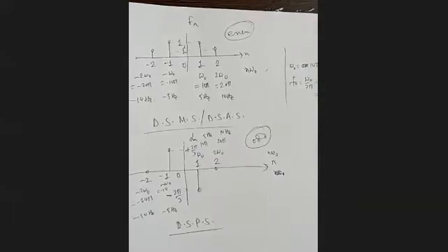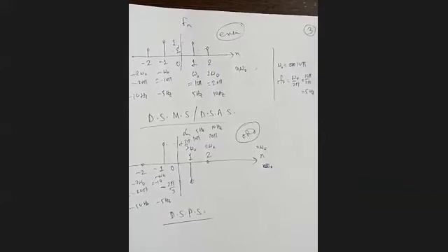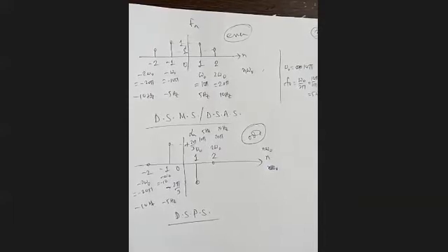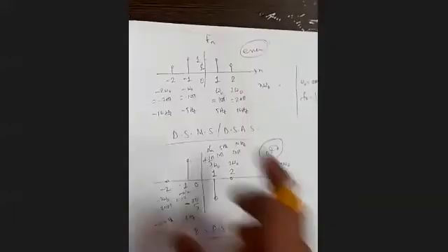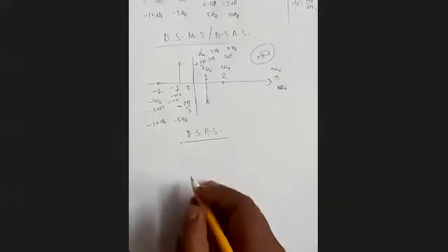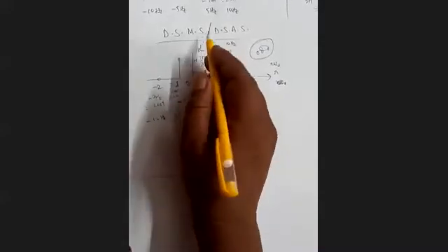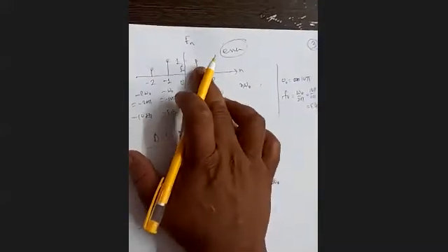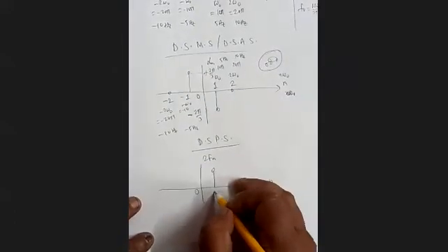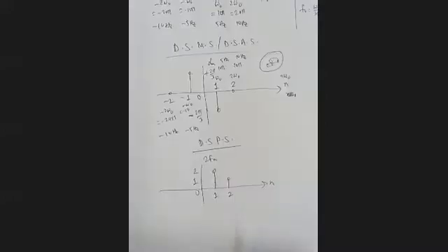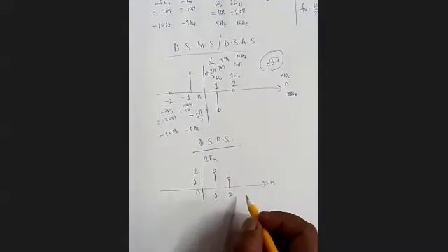Now in Fourier cosine series, we find that our magnitude of cosine term is 2fn, not fn, 2fn. So it has to be doubled, and negative part will be removed for single-sided spectrum. So 2fn versus n. So just take double. Instead of 1, it will be 2. And instead of half, it will be 1. Okay, it's single-sided. Negative part is not there.